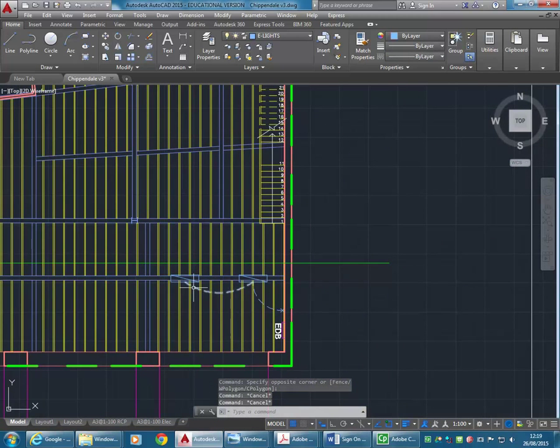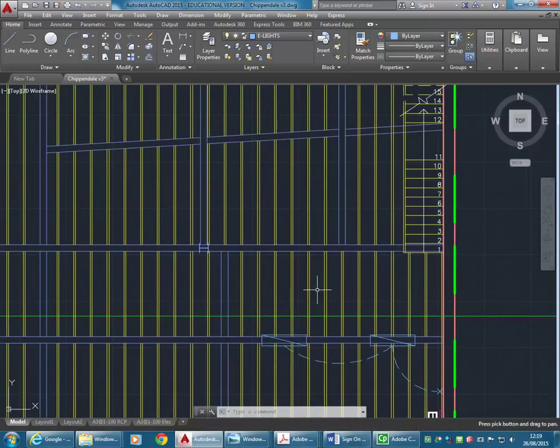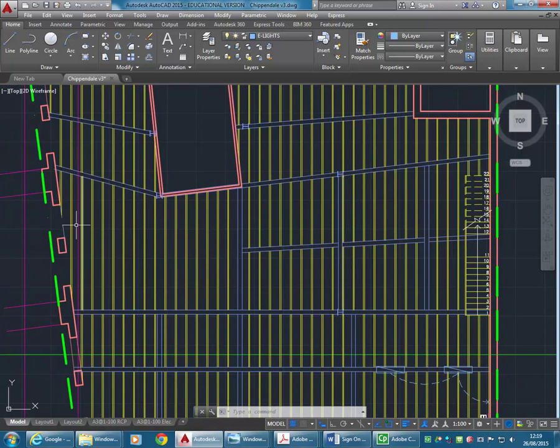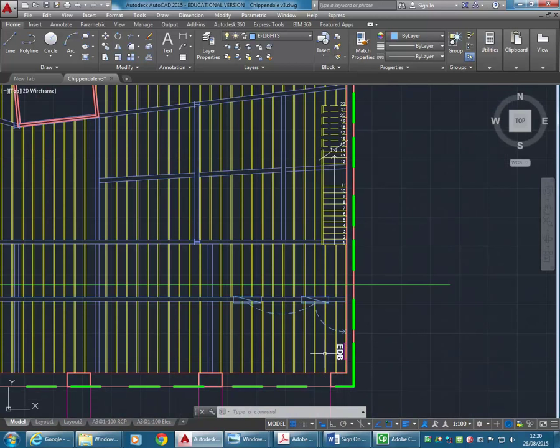And so every light that is turned on by that light switch just needs a dashed line connecting it, and so you might have another set of lights with another switch somewhere else, and that's the way you show your circuits. It doesn't need to show where the wires go, and so that's a common mistake. That's right, and that's the electrician's job.